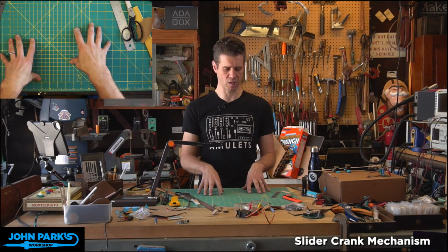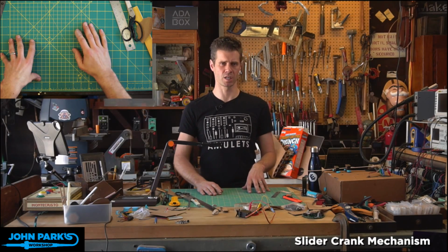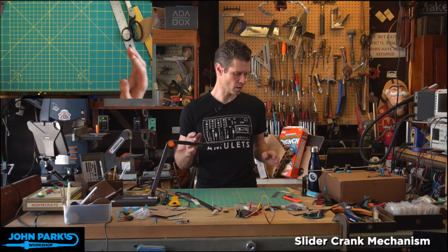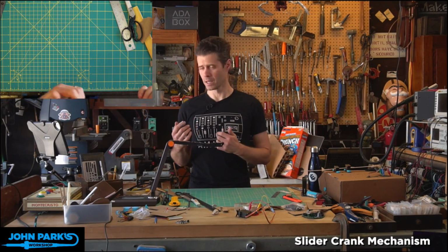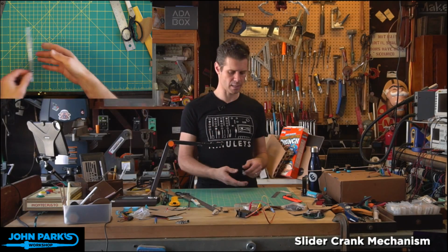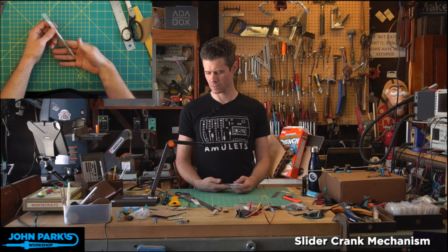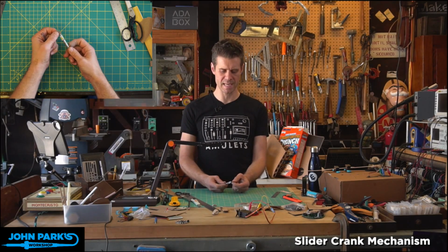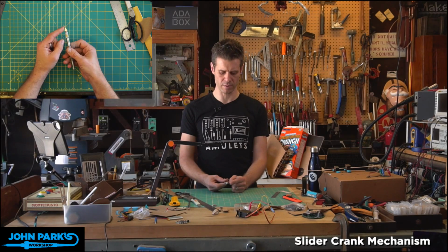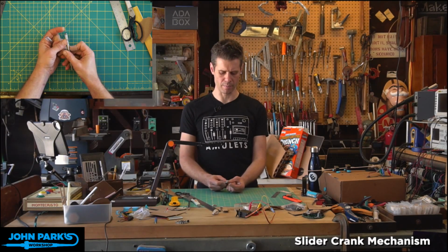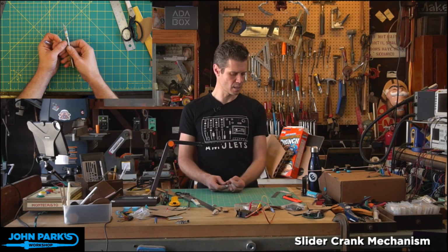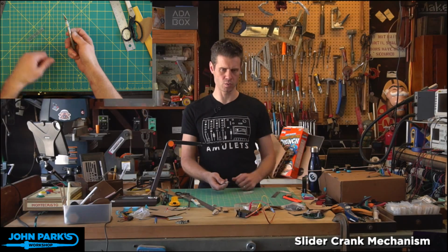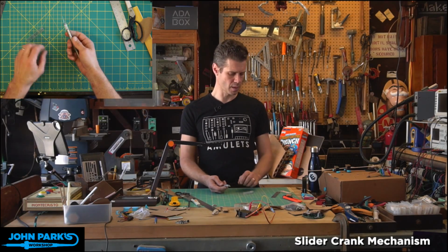So a cutting mat's a good idea. If you don't have one, you can lay down some magazines or newspaper or other sacrificial stuff. That's not a necessity, but it is nice to have. For cutting, you want a hobby knife like this little X-Acto I have here, but any brand of hobby knife. This is either a number 10A or number 11 blade, which tend to be the common ones that come with it, and they work great. Just get yourself a supply of replacements so that you stop using them the moment you feel that they're dull.